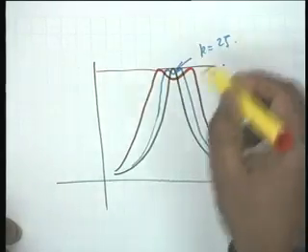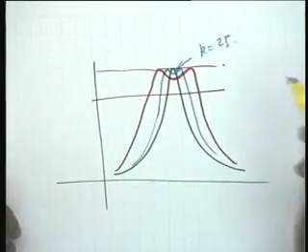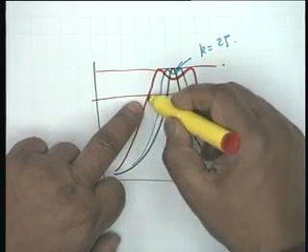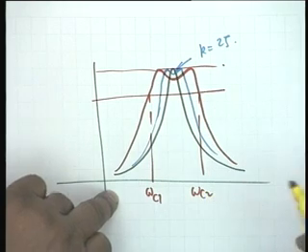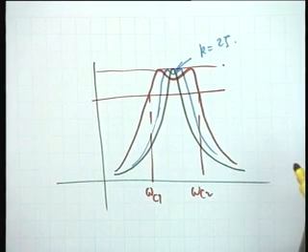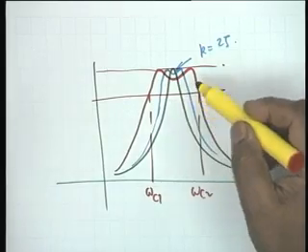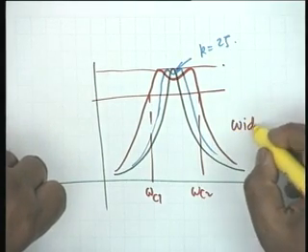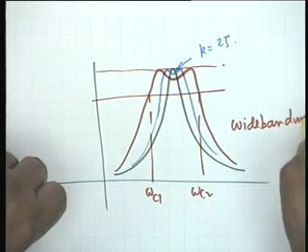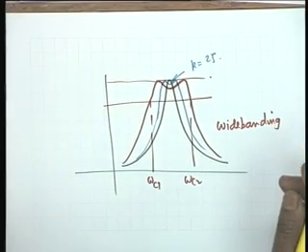Okay. Now what I said was the case would be of maximum interest when, between the two half power frequencies omega C1 and omega C2, the amplitude response, the magnitude response lies within 3 dB. If this dip goes below 3 dB, then we lose interest. Okay, and this is used for so called wide banding techniques, wide banding.